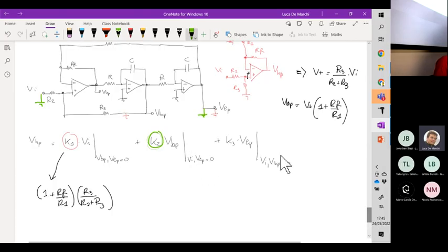A conventional voltage divider expression. What is the appearance of the green circuit? Okay, the green circuit is something like this. We have VBP, which is the input, attached to resistor R3. Then R3 is facing R2, which is then connected to the ground. Altogether, these two devices are connected to the positive input of the op-amp.